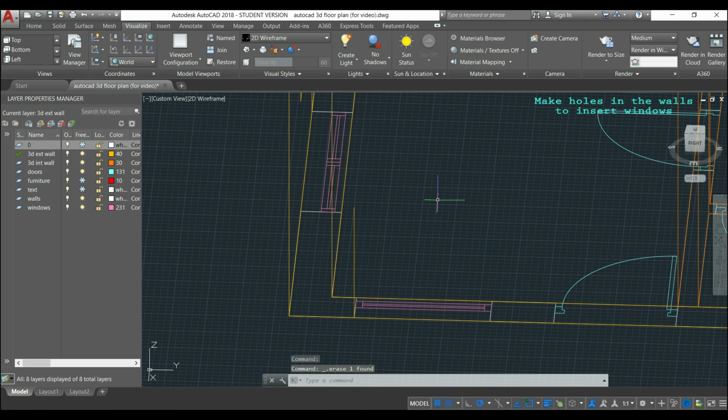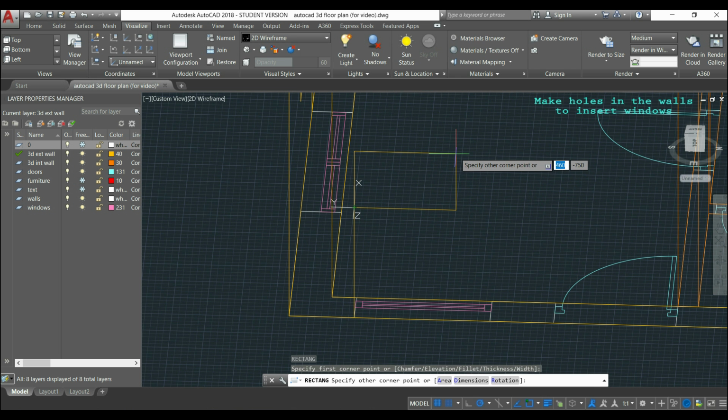Now I want to focus on another issue that sometimes happens. It's regarding the UCS coordinates. As when I'm drawing in 3D I'm changing the viewing plane so often, sometimes the UCS coordinates change the direction automatically. So you just need to pay attention to the current position of the axis.